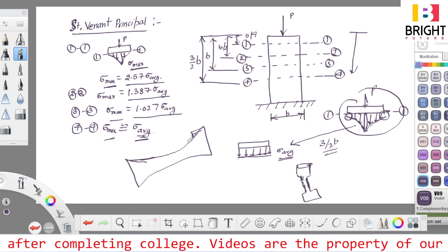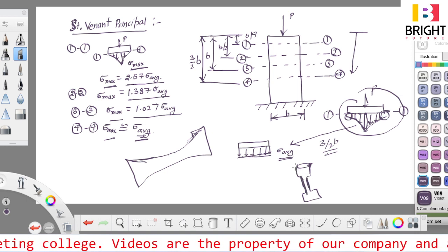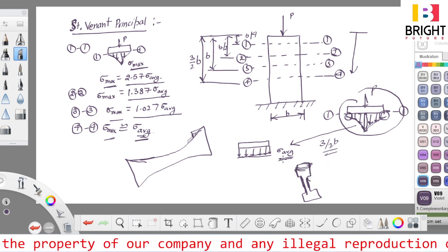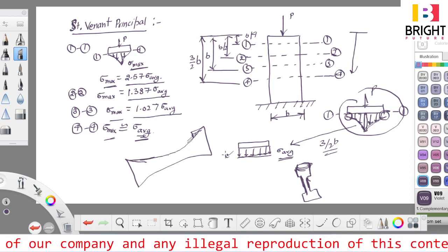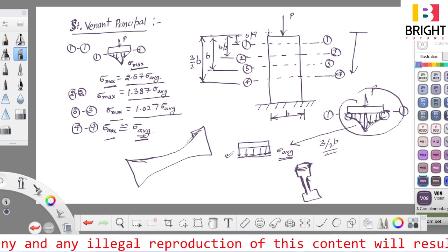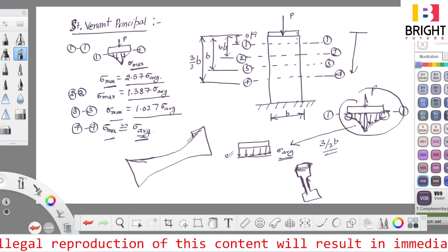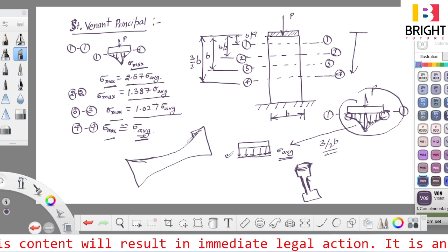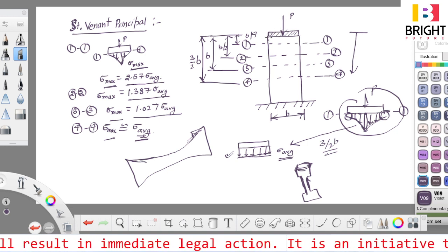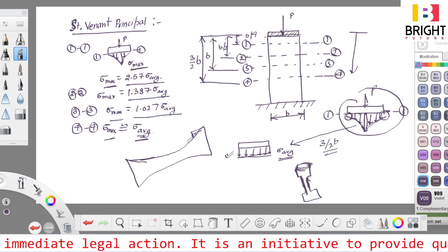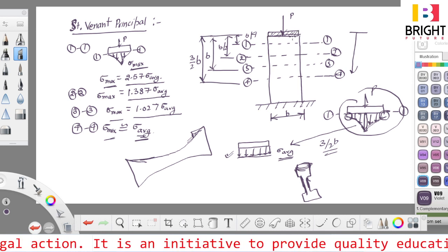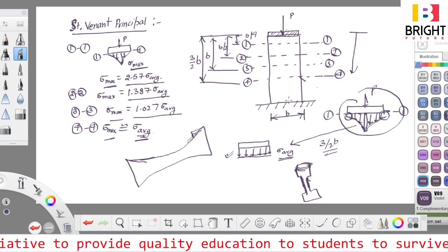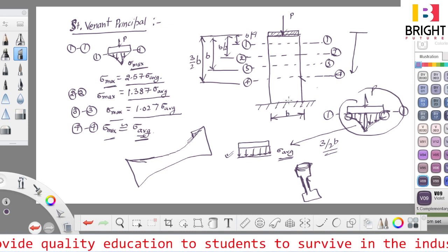At endpoints the diameter is more. However, to ensure that the stress is uniform all over the element, we can put an extra plate over this element and apply load over this plate rather than directly on the element. By providing this plate, we are converting these stresses to be more uniform rather than non-uniform, right? So this is what Saint Venant's principle says.